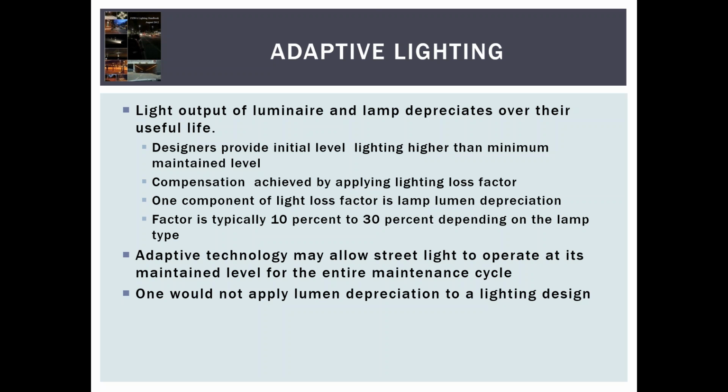Variations of lighting is not recommended in all lighting scenarios. For example, signalized intersections typically include pedestrian crossings. Pedestrian conflicts with vehicles are very likely at signalized intersections, and lighting should remain the same throughout the night. Mid-block crosswalks: the same rationale for signals applies to mid-block crosswalks.